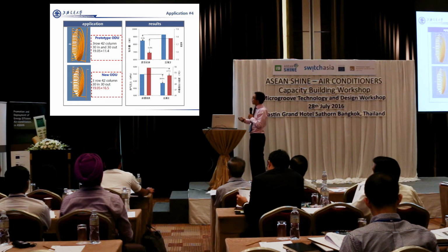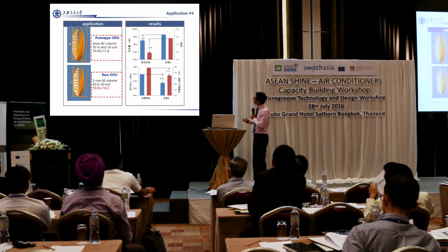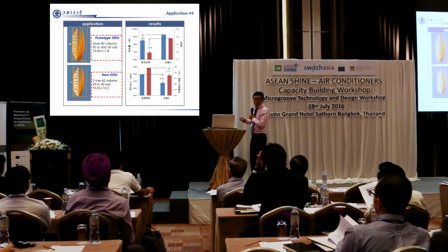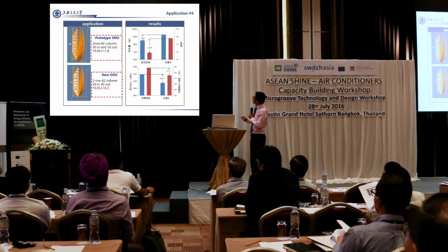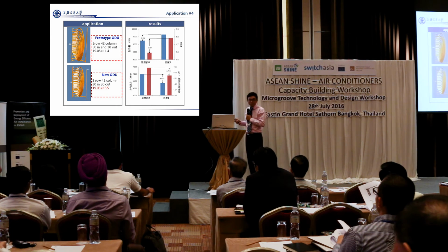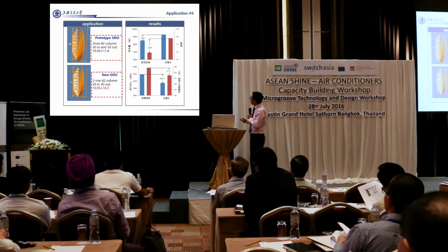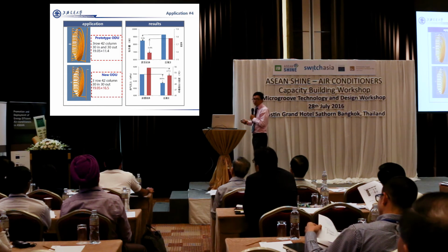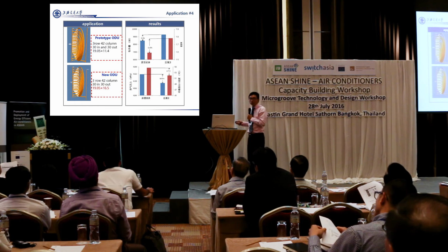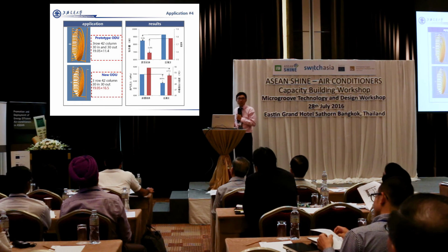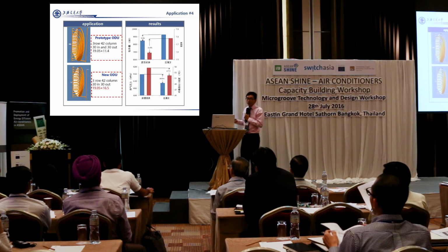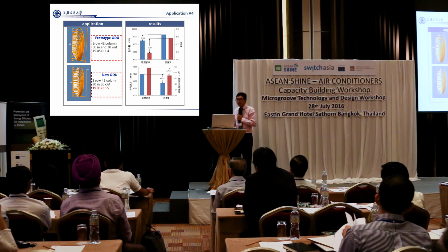As we extend our fin, our cooling capacity increased 9.5%, and our energy efficiency increased 11.9%. More importantly, our discharge pressure decreased 60 kilopascal. So for T3 conditions, especially in the Middle East, India or Thailand, the very hot regions, a wider fin for the outdoor unit is very useful.